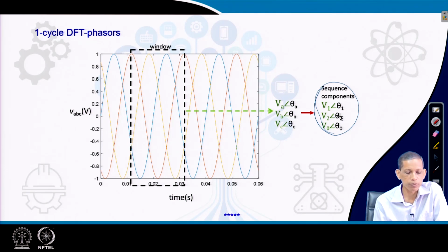So, what you learn from this is that for different current and voltage signals, the one cycle DFT algorithm, which uses the different sample values and the corresponding Fourier coefficients, can estimate the fundamental component very efficiently using the phasor estimation principle, and this can be used for the relay decision making process.